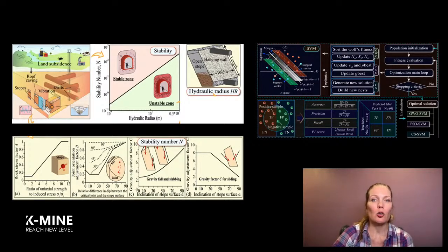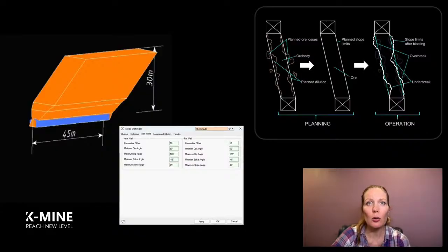Every candidate stope generated from the block model is automatically evaluated in stability space, and if it falls into the supported or unstable zones, its dimensions are adjusted until it fits within the acceptable region, or a backfill requirement is added as needed. So this matters precisely at the geometric level.